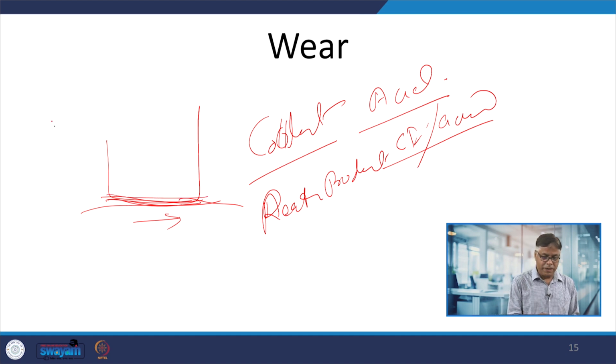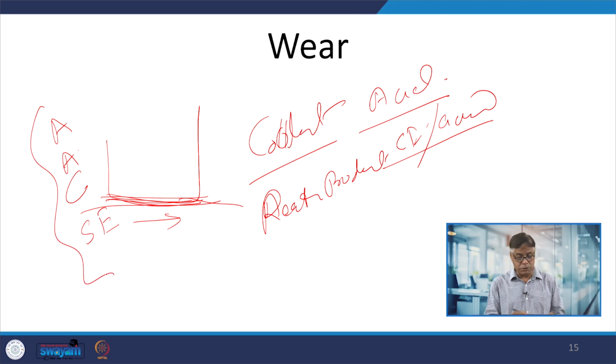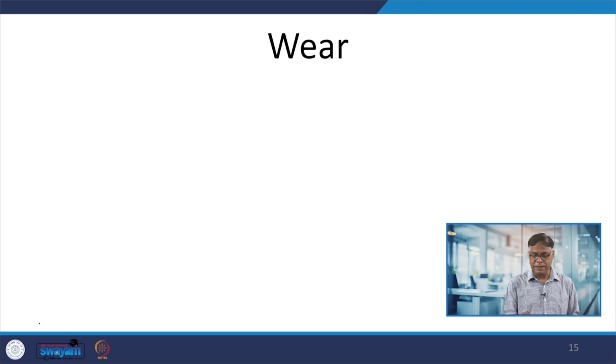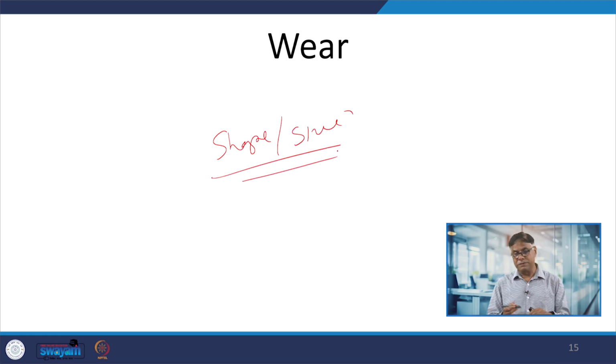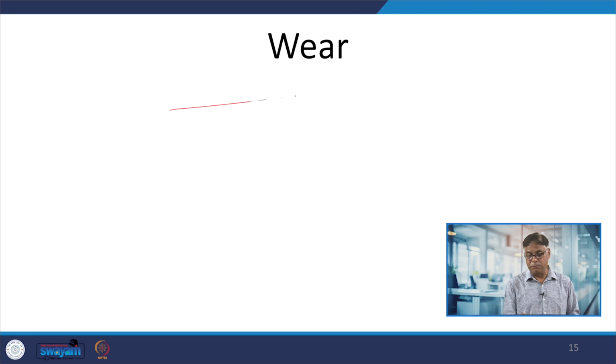So, that is how adhesive wear, abrasive wear, corrosion wear and surface fatigue wear, these four types of wear, are responsible for the removal of material from the guides. When material is continuously removed from the guide pieces, they lose their shape and size, and this change in shape and size makes their functioning difficult, so they may not be able to guide the bar directly and properly into the rollers for the rolling purpose.